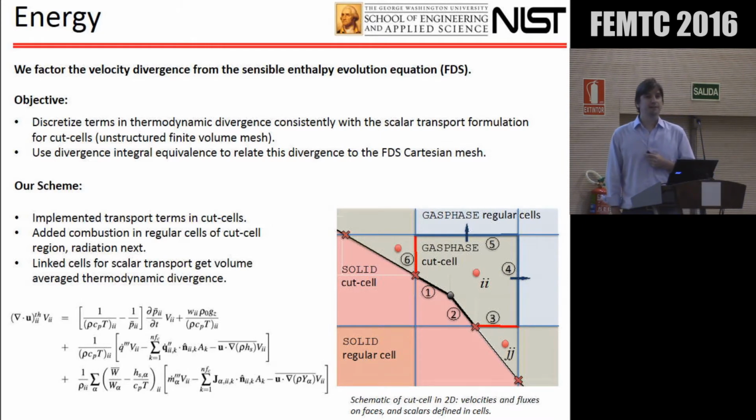And we have to discretize each of the terms from that expression. Here I put what the expression is. Looks pretty ugly, but there are all these fluxes, mass fluxes, and of course heat fluxes and heat production due to combustion, etc.